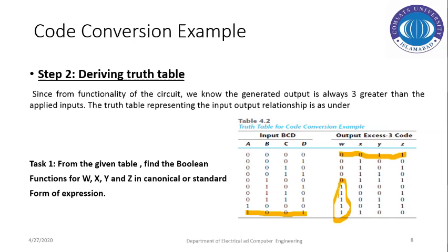At that specific time instant, we're going to see the inputs, and represent those inputs in the minterms or maxterms formats, and we're going to add them or multiply them depending upon the form of expression we are converting. This is what you're going to perform for task 1, which also carries the revision process for representing an expression in a canonical or standard form, and how we extract that expression using the truth table.